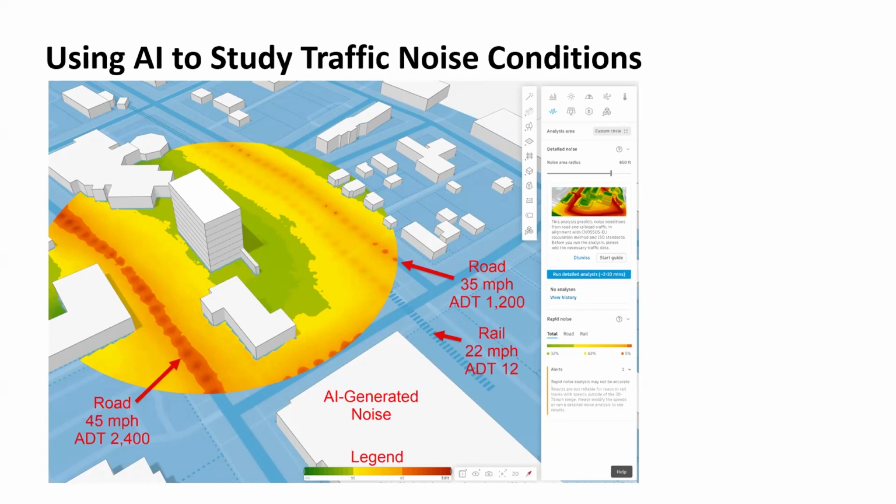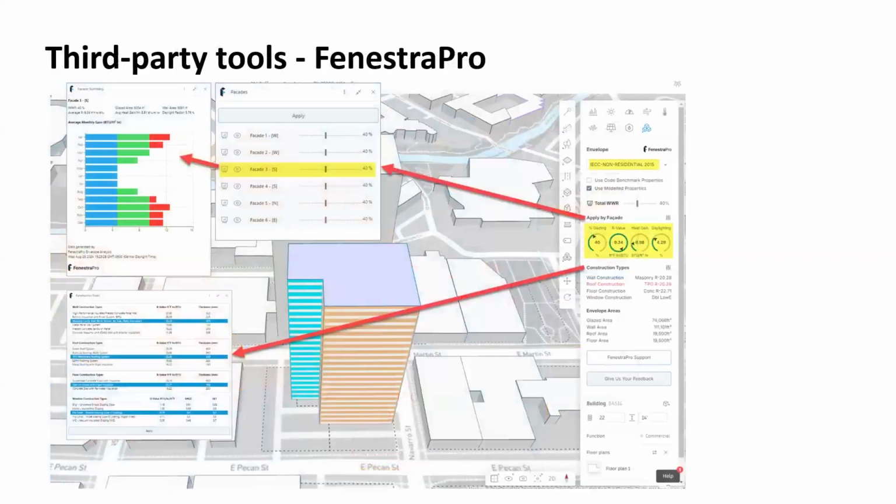And then when you run the analysis, first there's an AI version that's doing it in real time. Then you can see the blue button on the right. When you hit the 10-minute analysis, it'll project a heat map onto the ground and the facade of the building in decibels to tell you how much noise is being created.